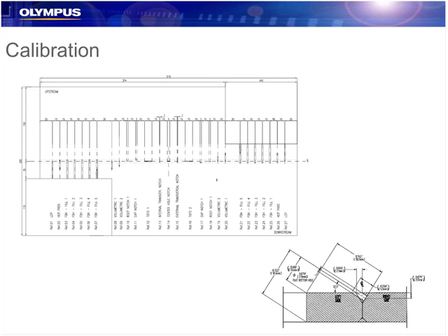Here's just a bigger look. So if we have a typical pipeline job, it might look something like this. It's typically a series of notches as well as flat bottom holes for each zone, volumetric reflectors, as well as fusion type reflectors and ID and OD. And then each one of those reflectors will be designed with the zone in consideration. So here we see a bevel type flat bottom hole. And very accurately, these are placed at the proper angle to replicate a defect that might happen on that fusion line.